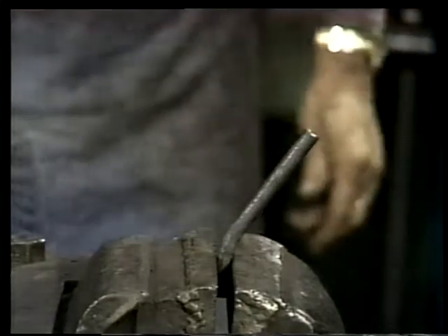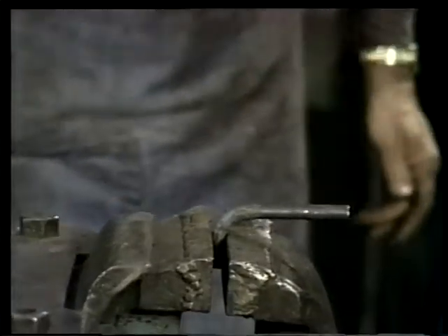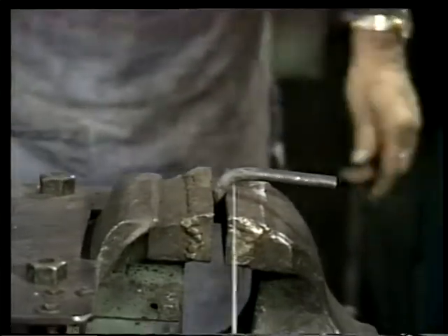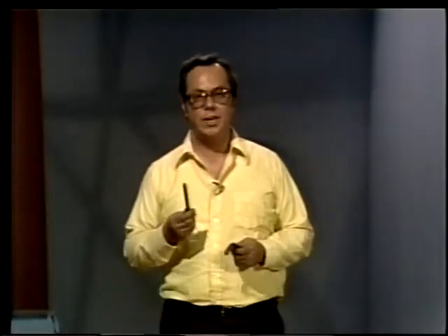To see how malleable the untreated piece is, we clamp it in a vise and hammer it until it bends. It didn't take very much effort at all to bend it over 90 degrees. Now that we've seen how soft and malleable an untreated piece is, we're going to see what heat treatment does to the rest. Let's take a look at one typical example of how hardness and strength can be controlled in a metal.